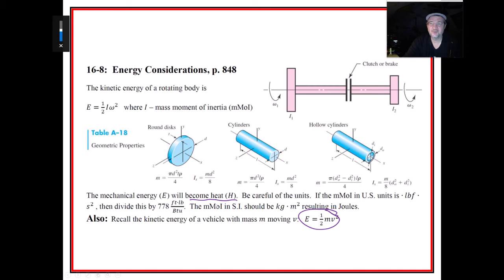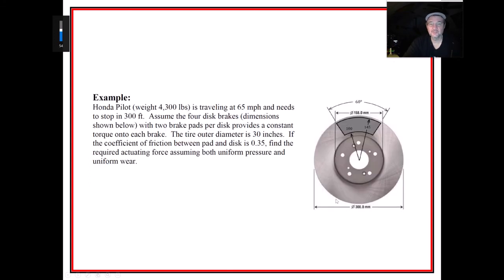A lot of times it's almost worth your while just to stick with SI, because we have various things that we have to worry about. And do I divide by gravity or not by gravity? And then do I use the thermal equivalent of mechanical work right here, or the mechanical equivalent of heat, the 778 foot-pounds per BTU, something that you have to use to connect them. In SI units, joules are the same thing as a Newton meter, so it's pretty easy to jump back and forth. But US units are just inherently screwed up.